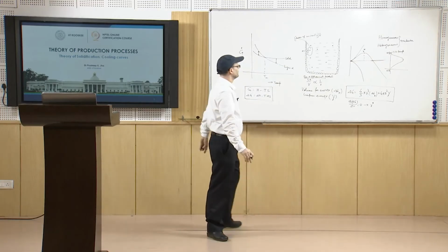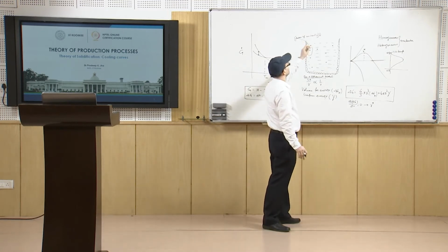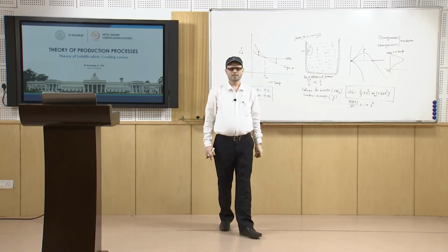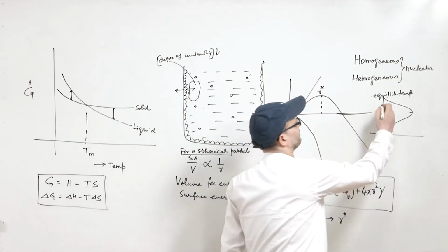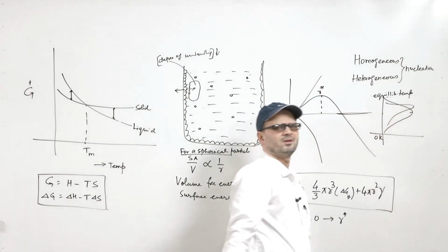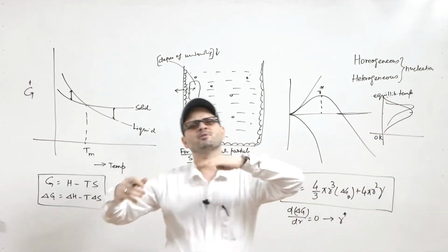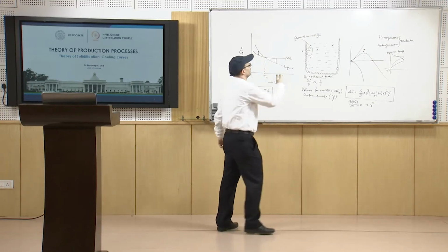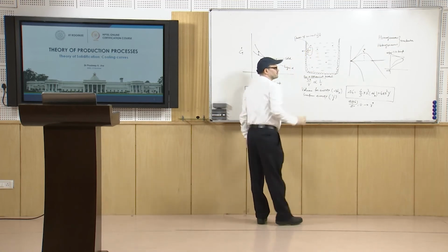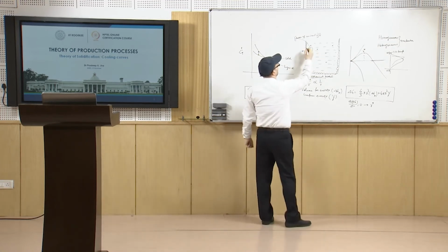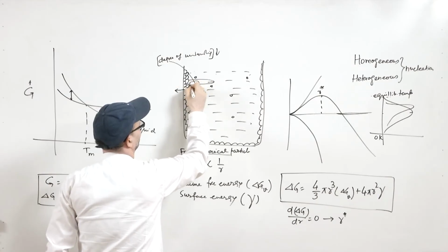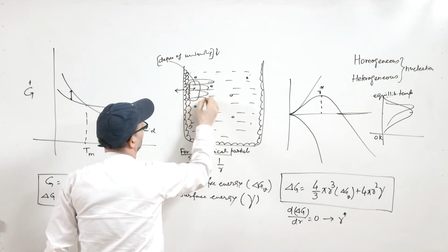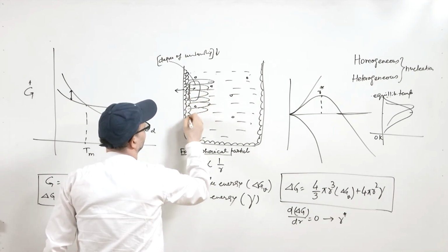So, what happens is that if the undercooling is reduced, then the rate of nucleation also decreases. But then there is another graph of the growth, which is similar, but the growth maximum is somewhere here. On the higher side the growth predominates. So, what happens in those regions is that nucleation stops and then the growth proceeds. After a few initial layers, the growth of the layers starts, growth of the atoms starts.